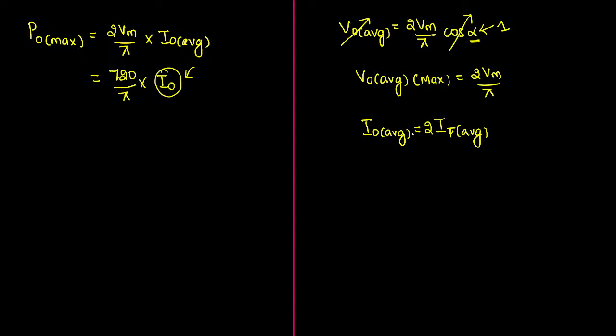But here what I am going to do is, we have to identify the maximum power that can flow from the source and then through the thyristor and then through the load, because the question is the maximum power handled by the converters, not only the maximum output power that is delivered through the thyristor.